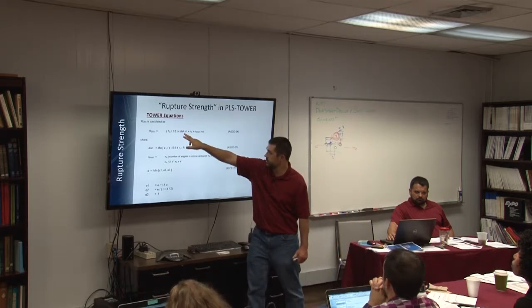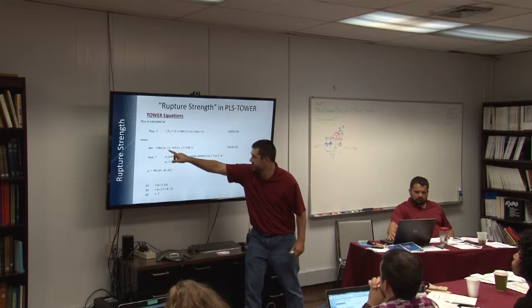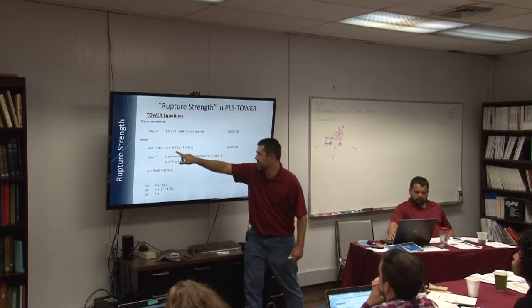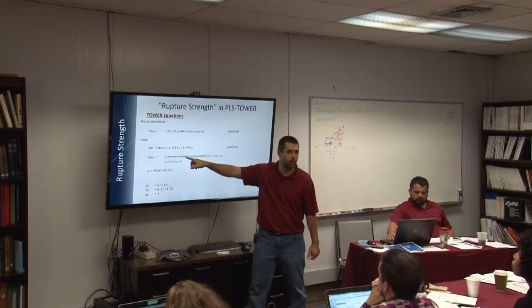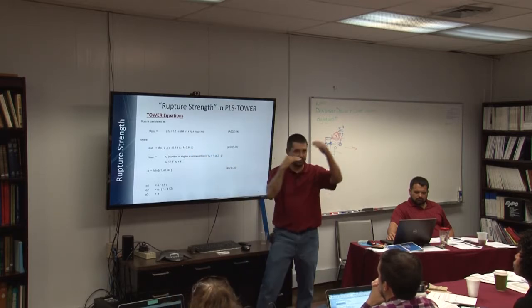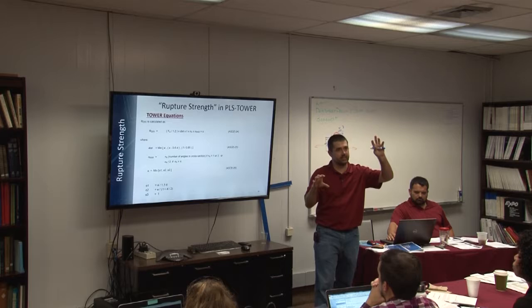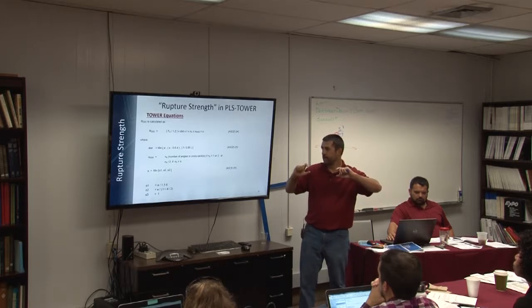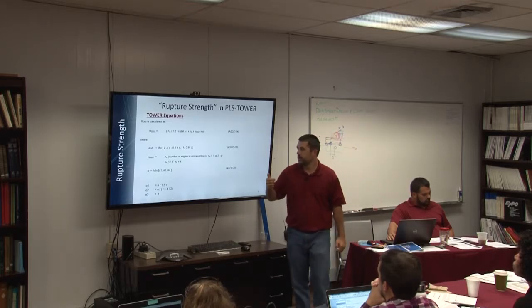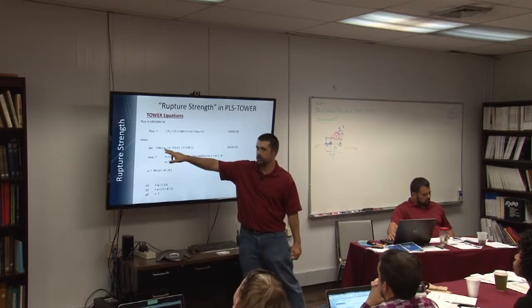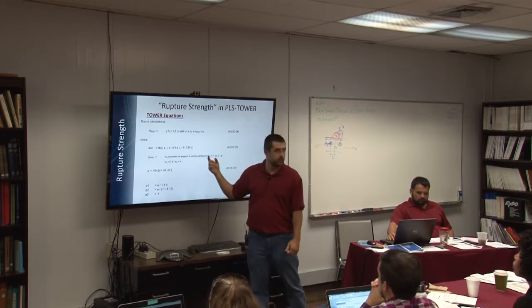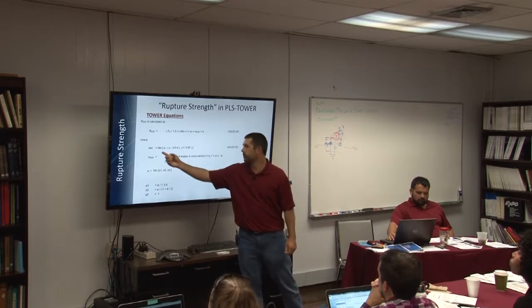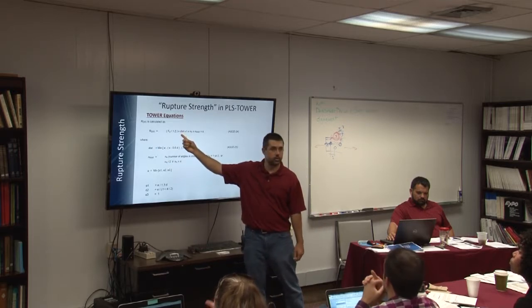Your distance is the minimum of your end distance, your spacing minus 0.6 of the bolt diameter, or your edge distance divided by 0.85. So what they essentially did was take all those different minimum distances, and they flipped them to be essentially equivalent to the end distance, and then you calculate the minimums of all of them. Whatever the minimum of all of them is, that goes into this equation.